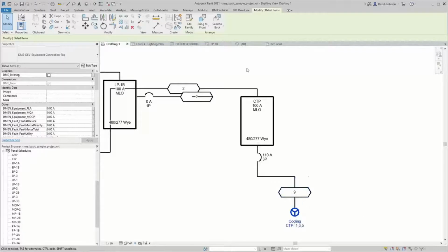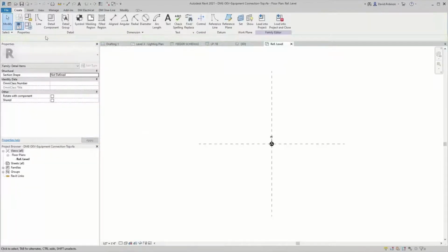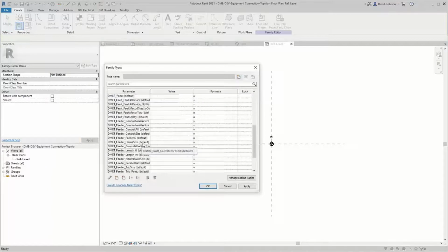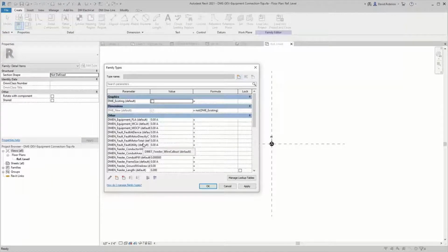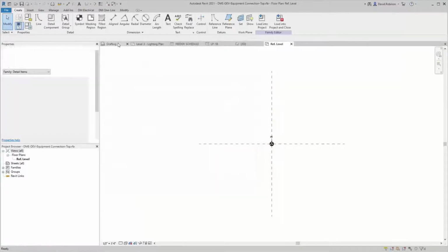By default, our families have a lot of the shared parameters. We chose to limit it. It's still like 30 or 40 parameters, but it's less than the 60 or 100 we could have put in there. So if there's a parameter that we have that you want to use, you can just add it. And if there are other parameters that you have, you can add them. And if they match, they will get transferred over.